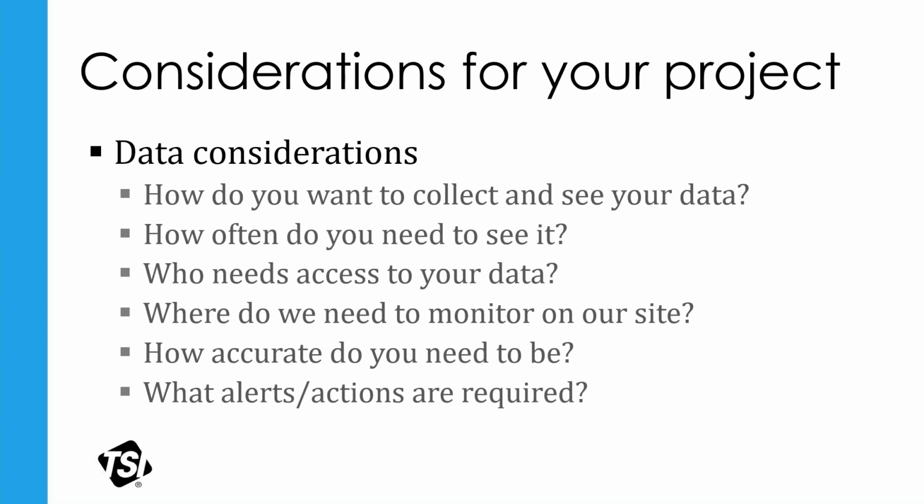Not exactly related to dust, but as far as need of information, some of you may recall that benzene leak outside Houston, I think about 3 years ago, in the Deer Park area. One of the complaints there was that they did have these different monitoring stations, but they were only recording or reporting data just a few times an hour. I think it was about every 15 minutes or so, and that just wasn't soon enough. They really wanted to have information sooner. So with your project, does that give you enough time to react to an issue, or do you need to know now? Who needs access to your data?